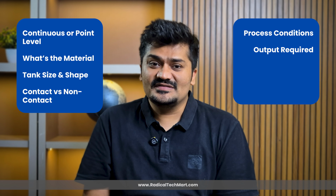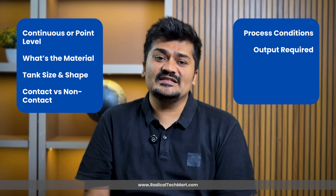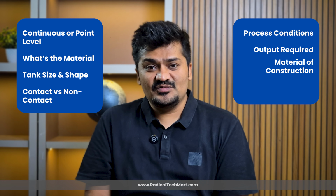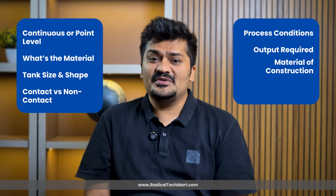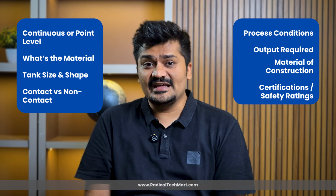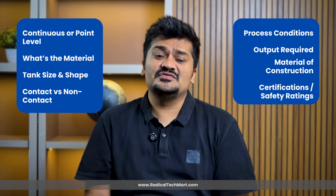Sixth part that you need to consider is output required, whether you require 4 to 20 milliampere output or relay switch or Modbus or HART for PLC SCADA integration. Seventh part that you need to consider is material of construction, that means MOC. Use SS316 or PTFE in the corrosive or chemical industry, or use PVC or PP for water and wastewater plants. Eighth part that you need to consider is certification, like safety ratings, ATEX approved, flame-proof, IP68, SIL based or industry or safety zones that you need to consider while you choose the right level sensor.